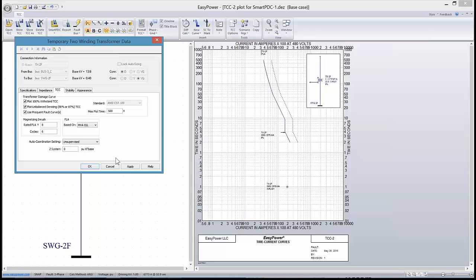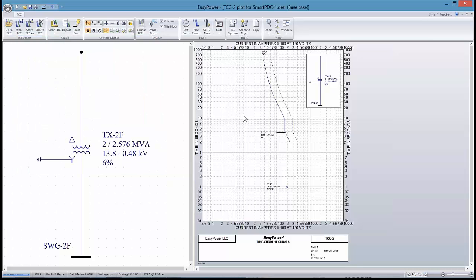But the intent is to be able to show you both a worst case scenario and potential derating aspects of the operation of the TCC of the transformer, because this applies in more applications than just the fault. And for purposes of setting up fuses and protective devices, you want to know where the time excursion is for a particular event.